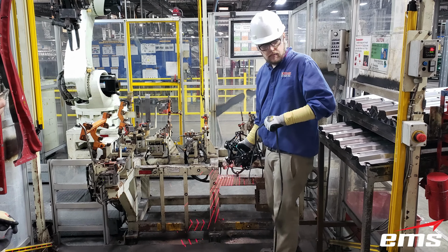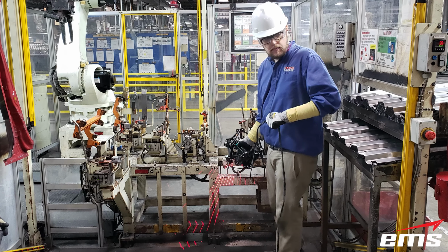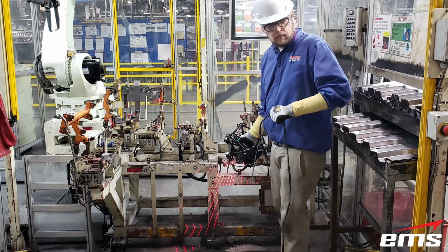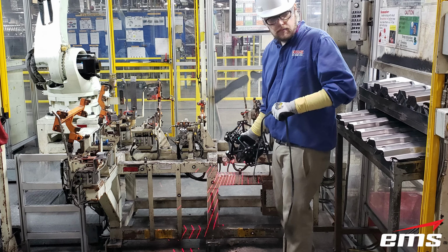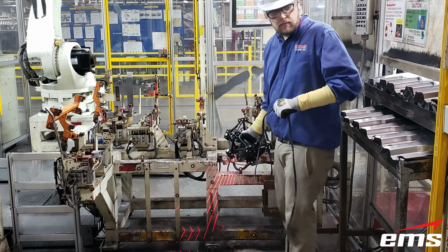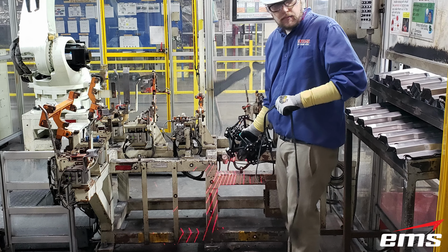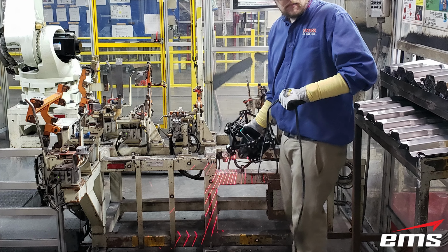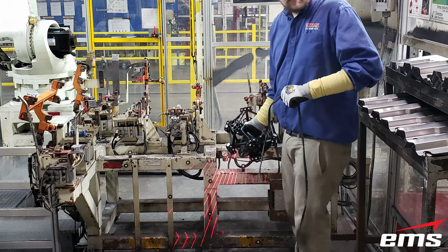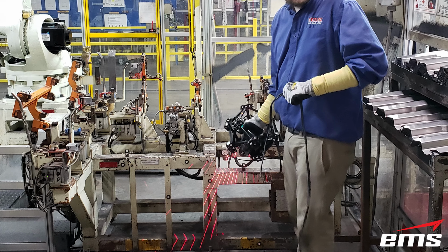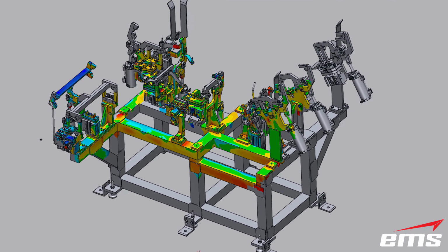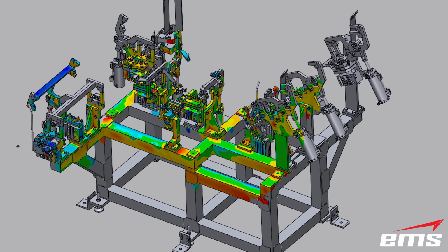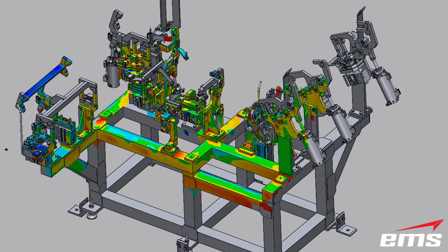Now, once we've established our coordinate system, we're going to go in and 3D scan the fixture. And we're only going to scan it where we need to. Basically, anywhere that the part nests or touches the fixture, any locating locations, locating pins, holes, whatever it may be, we're going to scan all of those areas so we can compare them back to the CAD model to make sure it is correct. So now what we can do is overlay the scan data on the fixture, and that should automatically come in the right orientation because, again, we've established that coordinate system.